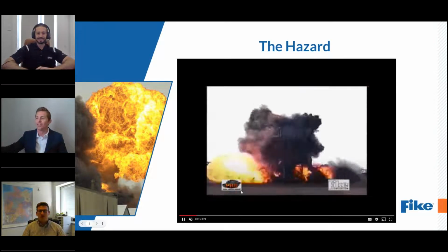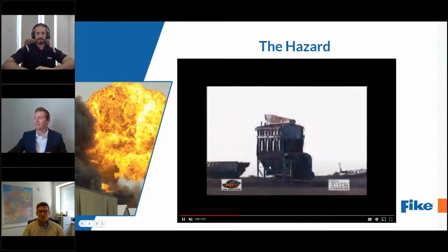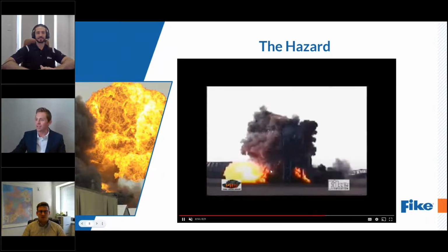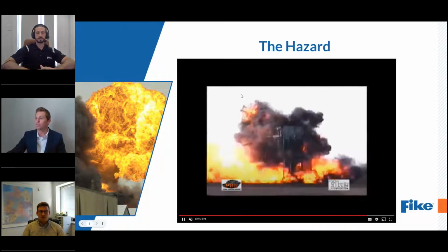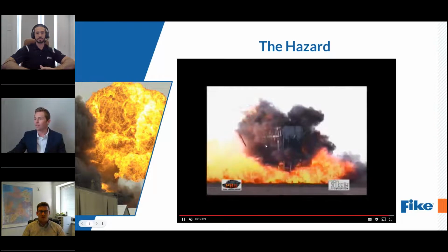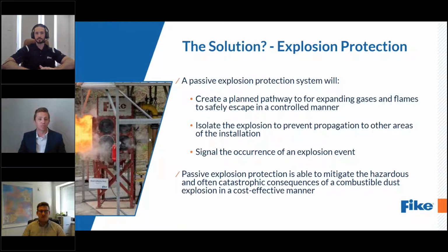Just imagine it going, okay, so this is slow-mo, so this is Red Hot Chili Peppers. But anyway, you can see the dust go into the dust collector. Here it goes, and it's unmitigated. It balloons out, deforms. Here comes the fireball. Here's a secondary explosion coming out the top for unoxidized fuel, and it's just a massive plume right underneath it. That's why explosion venting is required, or some form of explosion protection.